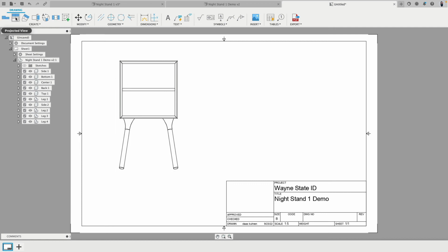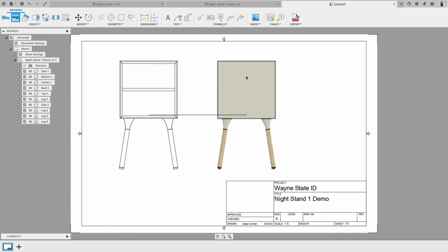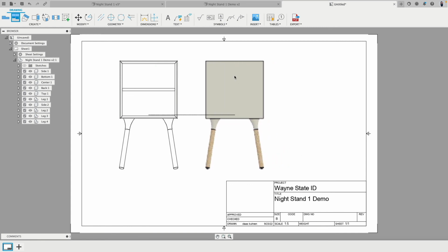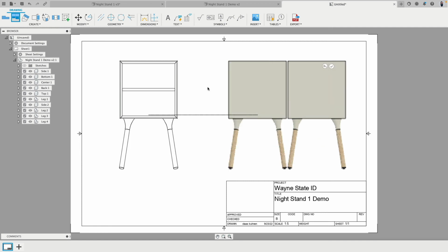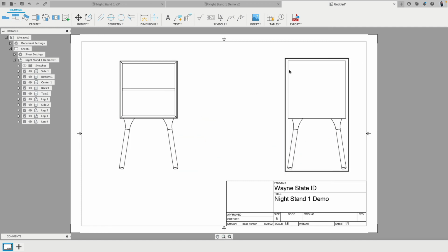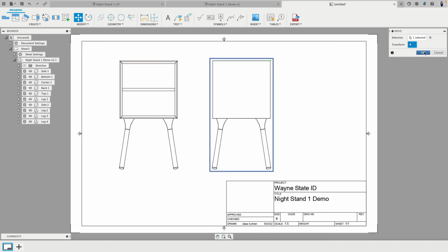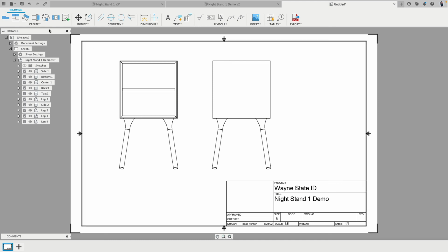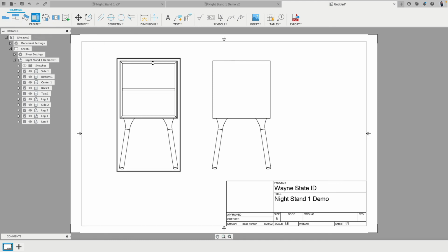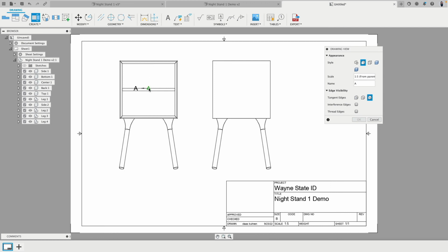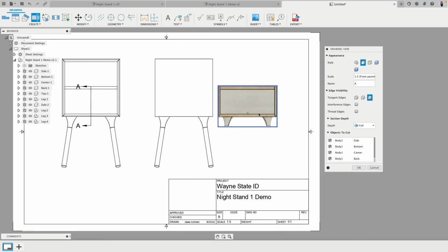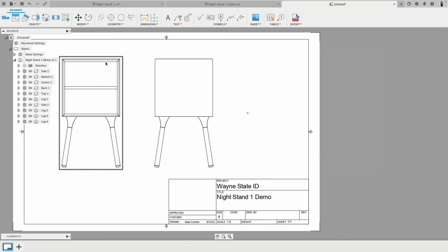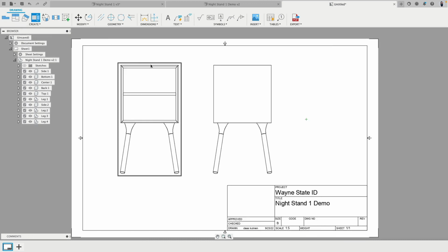Let's add a projected view of this to the side. Maybe there. Okay. This, I would like to maybe move a little bit backwards to there. Cool. Can we do a section view? Let's see. So from maybe this midpoint to midpoint. Okay. And there actually creates a section view through this part. So that's kind of silly. So let's do this one more time.